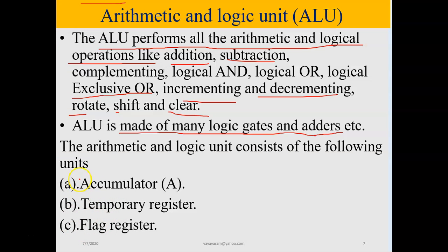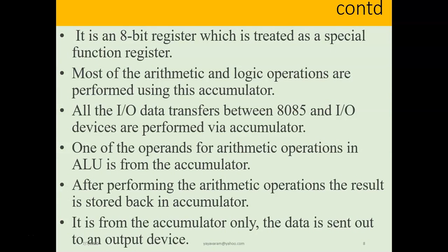Arithmetic logic unit. What is this first one? Let us consider now the accumulator. As I've already told you, what is this accumulator? It is an 8-bit register. Very important: the accumulator is an 8-bit register which is also treated as a special function register. What is the speciality of this? You come across it in the next line. Most of the arithmetic and logical operations are performed using this accumulator register.